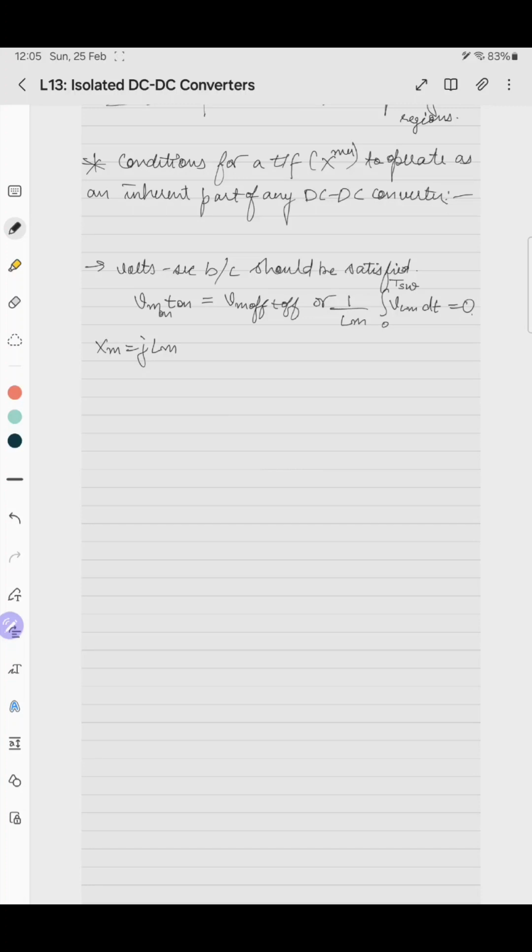For that electromagnetic induction, the transformer needs to first magnetize the core so that the flux flows through the core, and thus due to this rate of change of the flux, the EMF is induced at the secondary, and as EMF is induced and the circuit is closed, we get a current. So if there is a current, it means that power is transferred from primary to the secondary with isolation. So typically we want this magnetizing current to be very small. For the rated power transfer, the magnetizing current should be minimized.